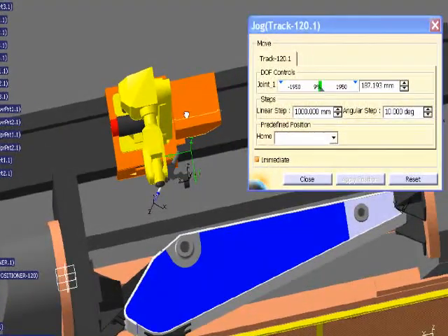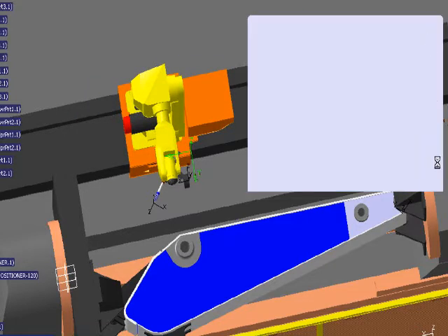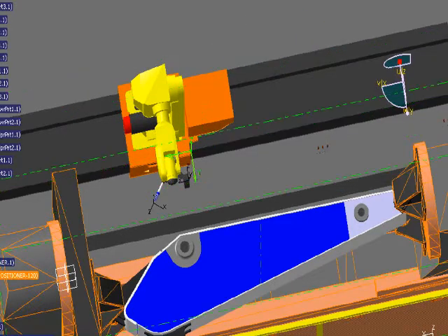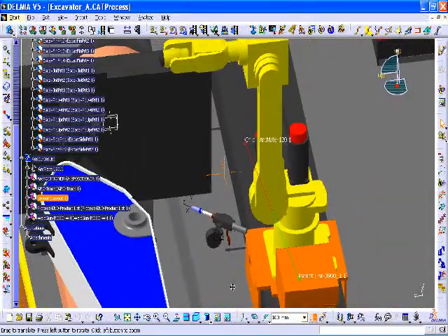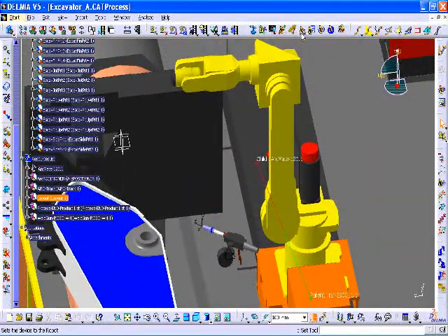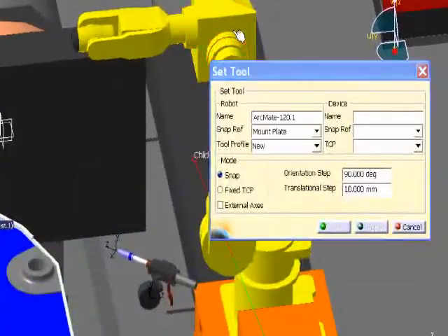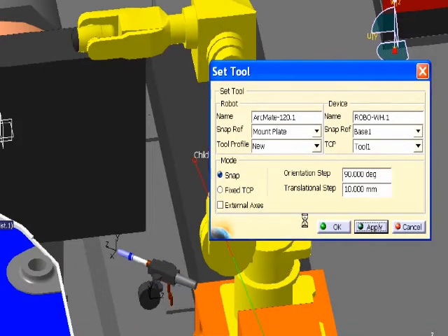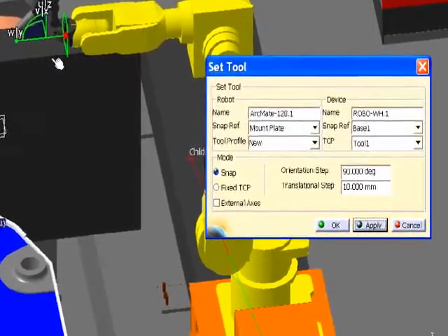The software also gives you the capability to build your own robot. Our gantry is also from the library, but you could create that from your CAD data. The next step is to attach the torch to the faceplate of the robot. After the torch is built, we open it in the device builder. We're not ready to add kinematics, but we can add the tool point location, and this will be automatically input into the simulation for the robot's tool center point.